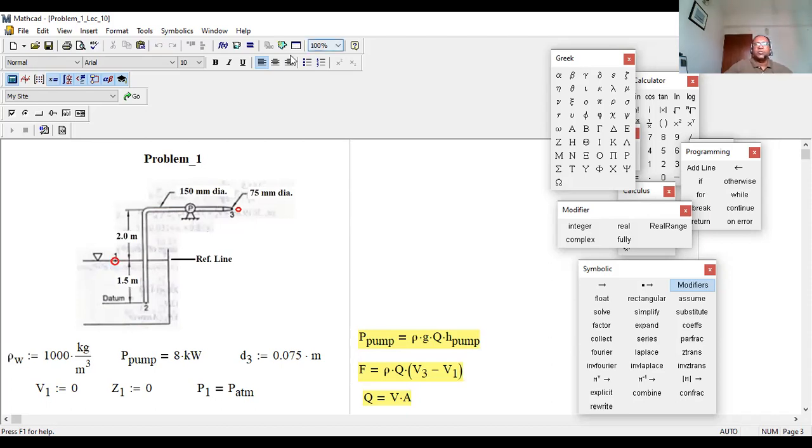But what we did, anyway, your question is a good question. I appreciate that you asked it. We apply Bernoulli's equation not inside the pipe. Point 1 is outside of the pipe, in the reservoir, and right over here. What is the reason? We are thinking, if there is no pump, would fluid come at point 3? Yes or no? Obviously no. But due to the pump, fluid is coming at point 3 with some higher speed. What is the reason? Because it is pulling, right?